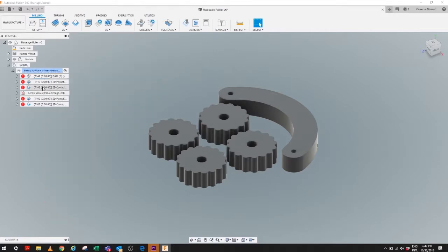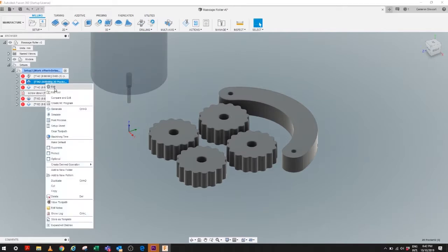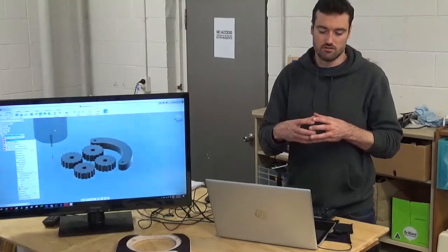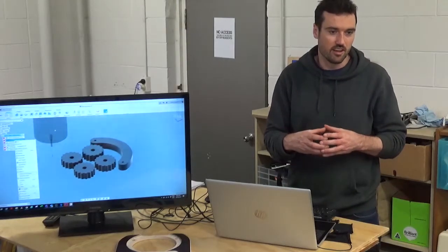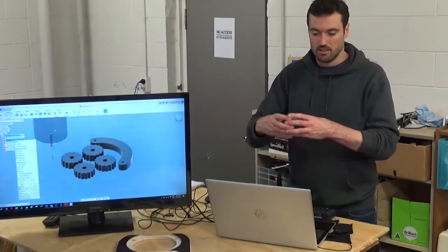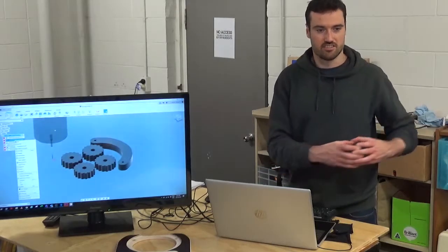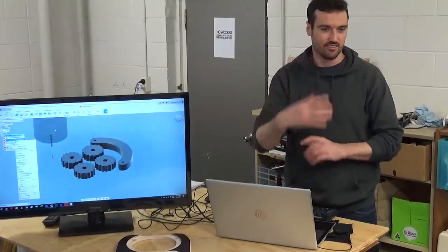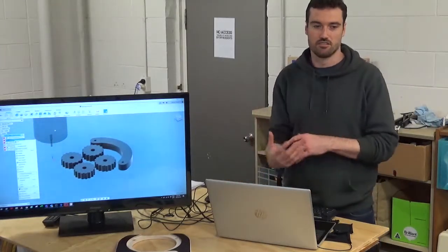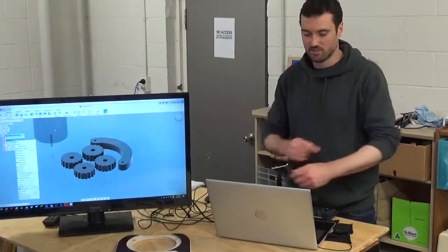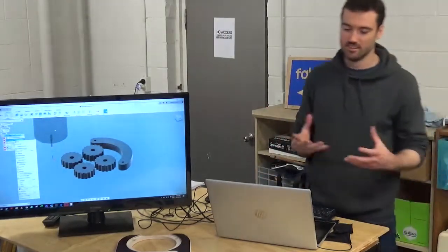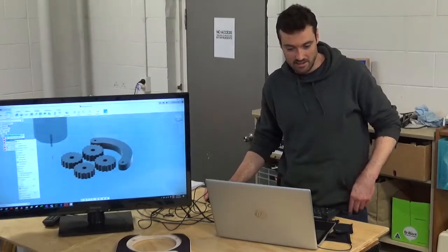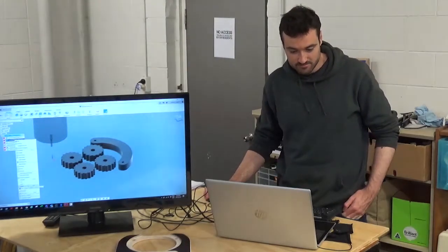I'm not going to use him. Cylinder, or is that like a whole tool? That's the motor. So the big cylinder is just to show the vacuum and the motor head. Basically, it'll do crash detection. So if you're trying to cut something and that circle hits something, it'll show a warning. If you went really deep and it caused a crash, it would tell you that. So don't do that. We can delete that one.